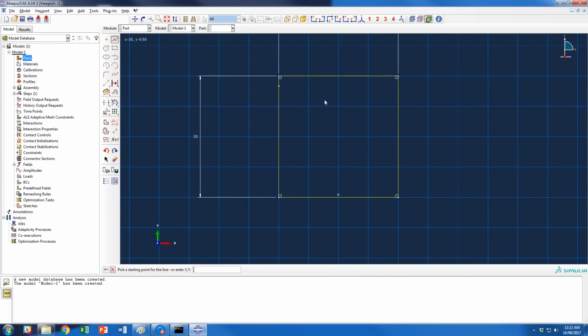And it's going to have a cross brace across it, so it's going to have one member that goes from there and then another member which goes down to there. And if you want to stop it from continuing to offer you a new line, just hit escape. One thing we note is that these two cross members will be joined in the middle, but currently they're sort of separate members, so we just want to split one of those.